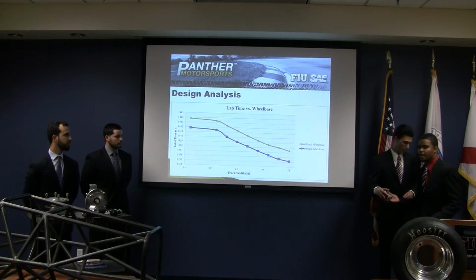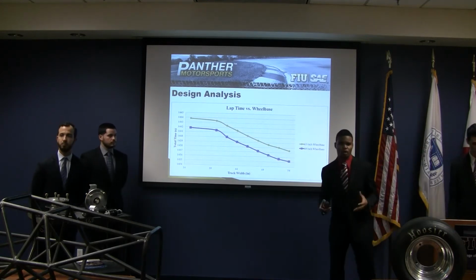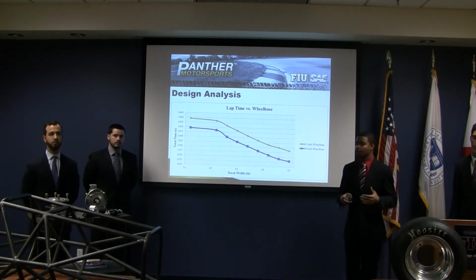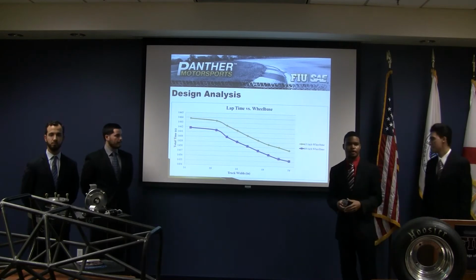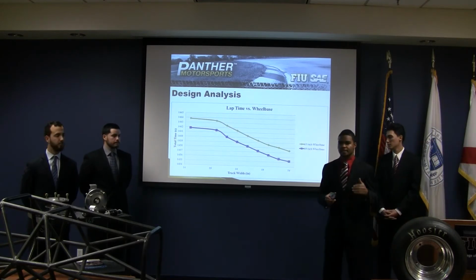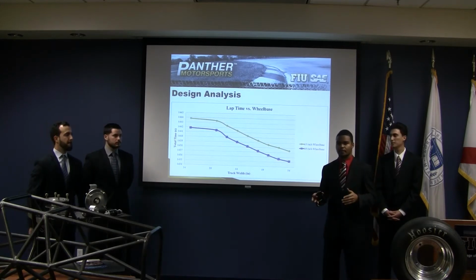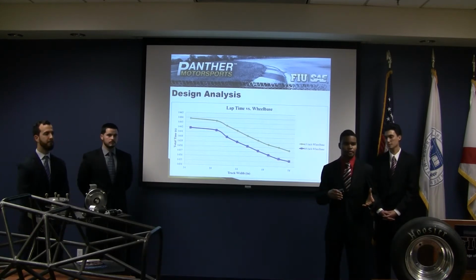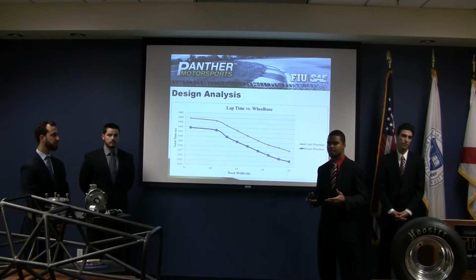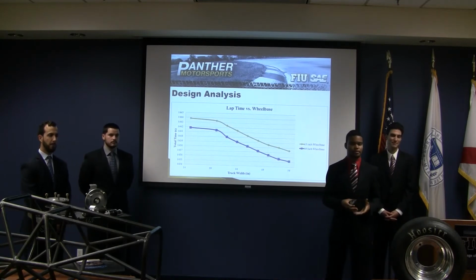Before developing any components of a vehicle, the overall design goals must be determined, some of which include the wheelbase and the track width of the car. The wheelbase is the distance between the front and rear wheels, and the track width is the distance between the left and right wheels. These affect how loads are transferred between the four wheels in any dynamic situation. Thus, they're important to consider in terms of performance.